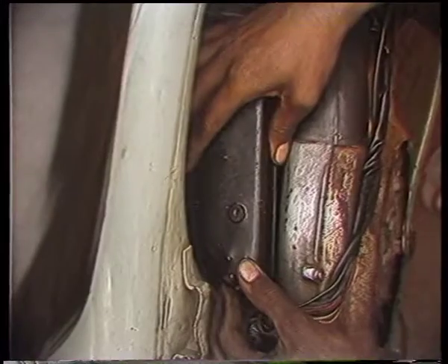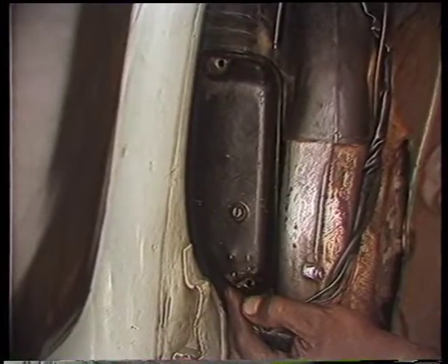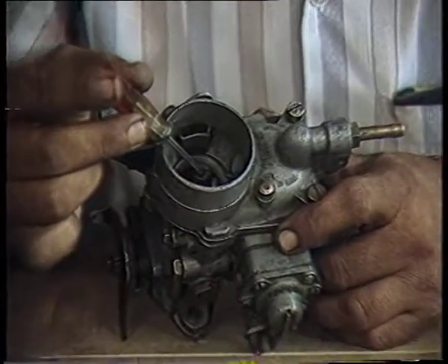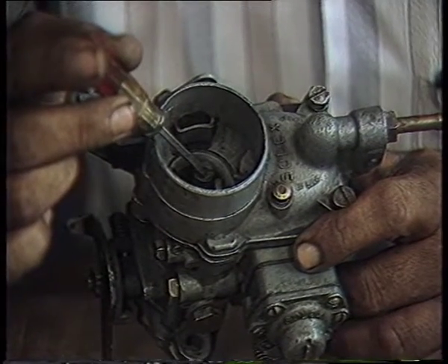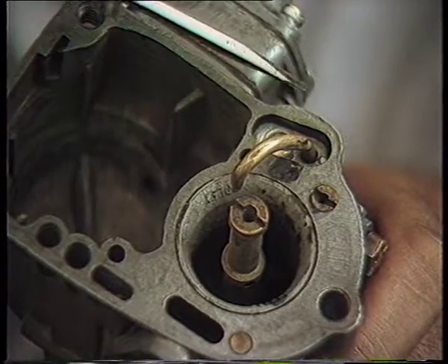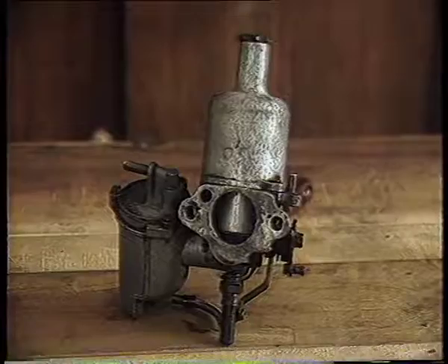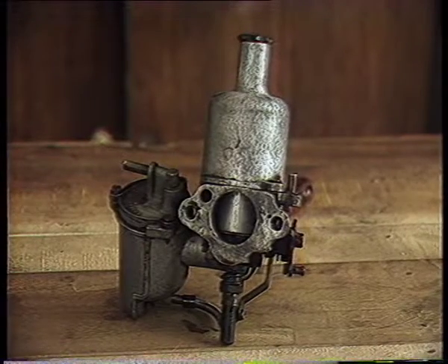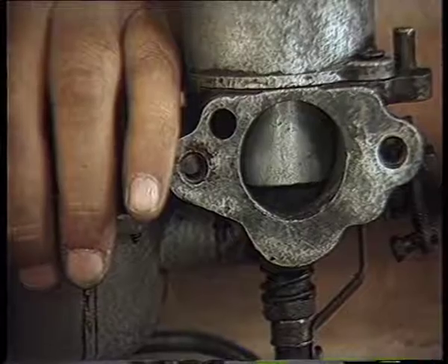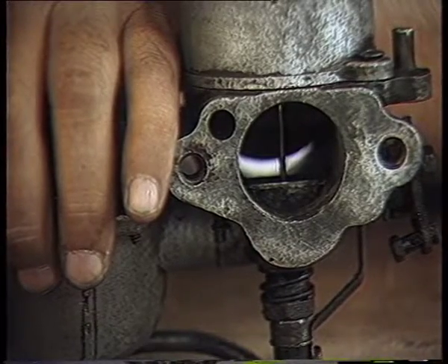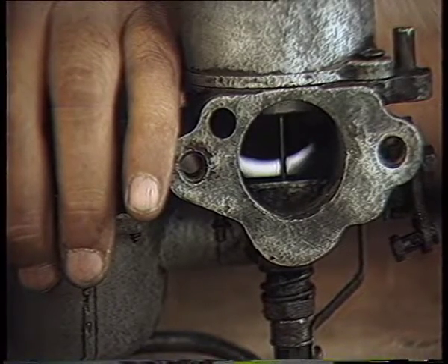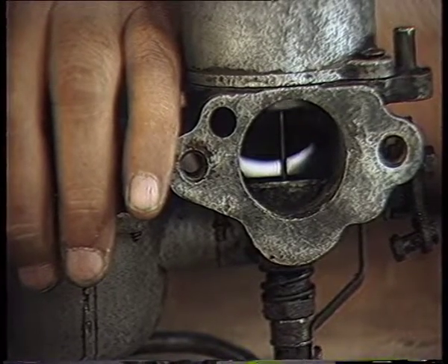Let us take a look at the two types of carburetors. This is the fixed Venturi variable vacuum carburetor. Here the varying volume and speed of air through the Venturi tube creates a variable depression on the jet. This is the second type, called the variable Venturi constant vacuum carburetor, where the Venturi size is automatically adjusted to provide a uniform speed of air and a constant depression on the jet.